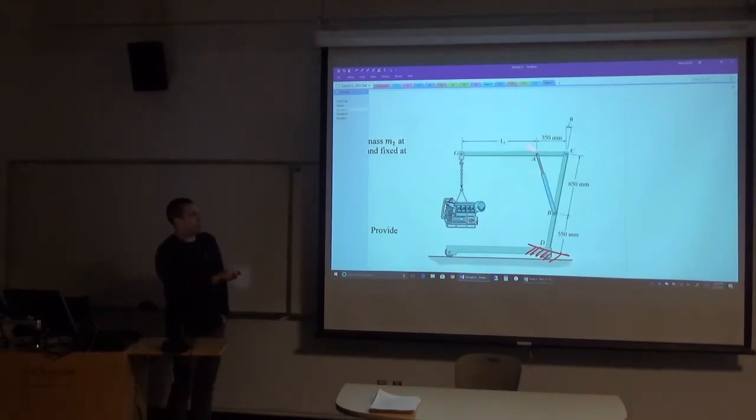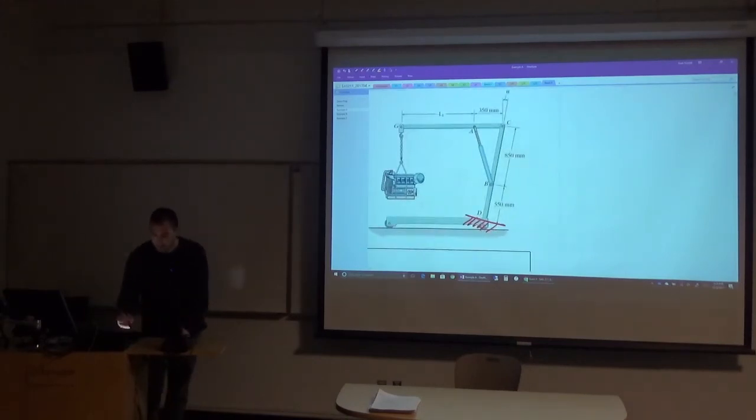Yeah, because this strut right here framing in is probably going to apply a force, right? It's completely possible that this might not be applying a force whatsoever, but we can't make that assumption yet until we calculate what the actual force is. So GAC is not a two-force member because it has this intermediate structure that's applying some force, ostensibly not at the ends of the structure. Okay, so as a result, let's go ahead and just draw what our free body diagram is going to look like. I'll draw it over here to the side.